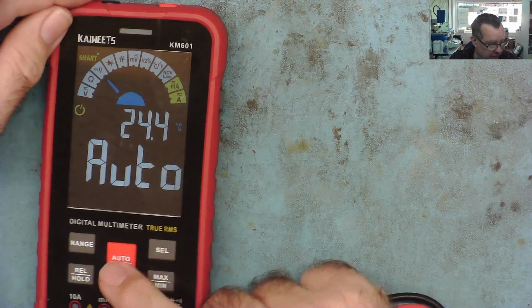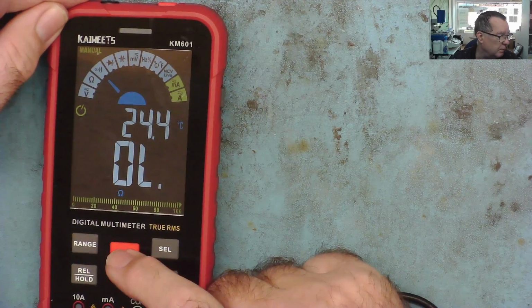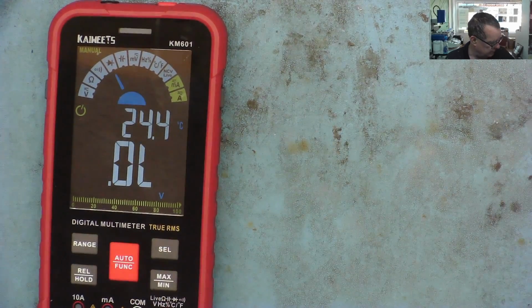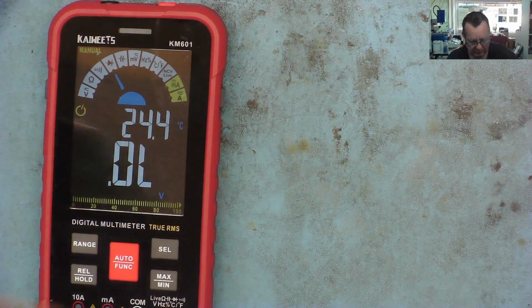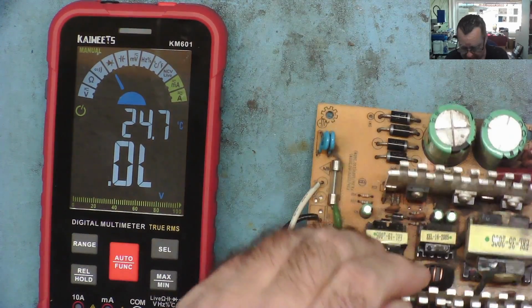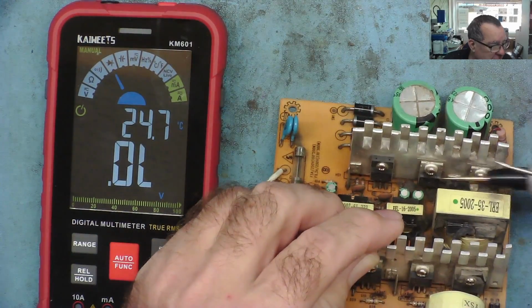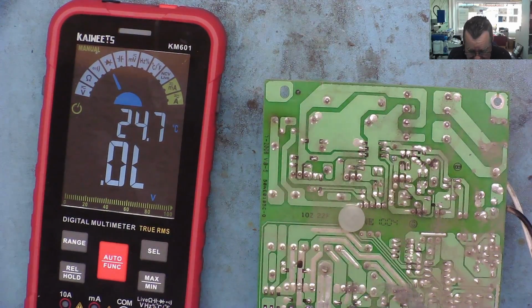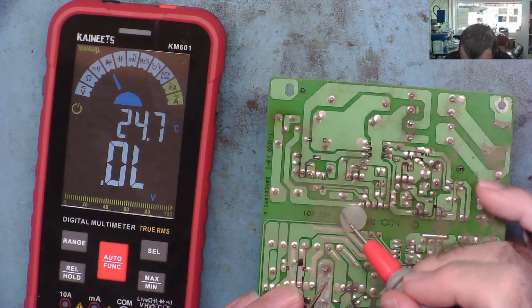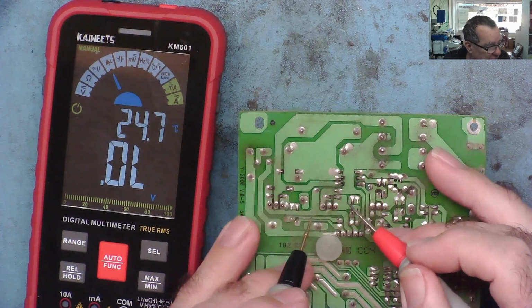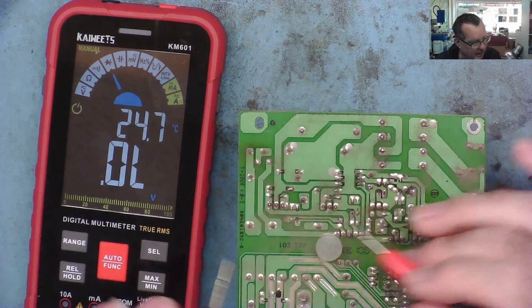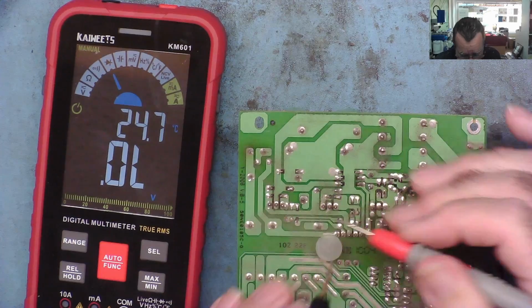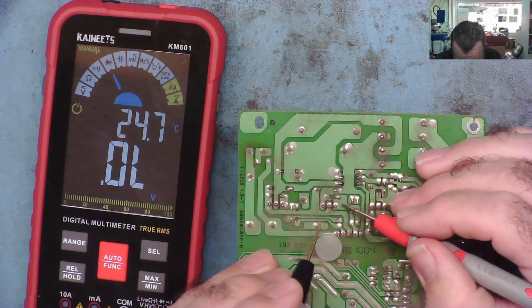And to do this, we need to use the diode mode on our multimeter. So we're in diode mode, and let's have a look. There's a few old circuit boards here. This is off an old ATX, and there are two transistors down here. Now, if we try to test these in circuit, I'll just find where they are. I can see 3 pins here. We should be able to see the semiconductor junctions, but we may not always be able to. So let's have a look.